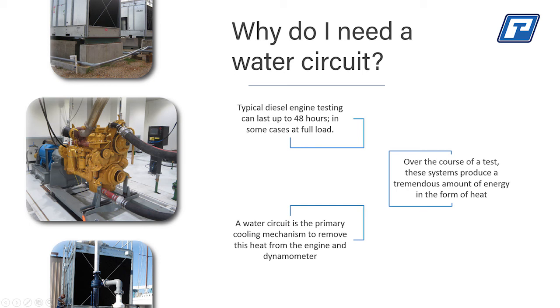So it's significant. Hey Rick, are they the only load device that needs a water circuit? No, water brakes are really one of 2 devices that need water circuits. So water brakes is one style of load device for loading an engine. Another device that is used for loading engines are water-cooled eddy current dynos. Significant difference between the 2. Some of our competitors sell those. We sell some water-cooled eddies. Definite price difference between the 2 systems.